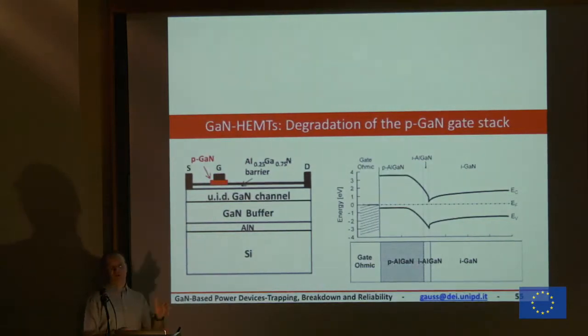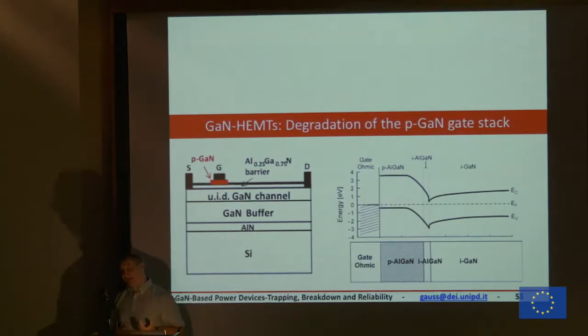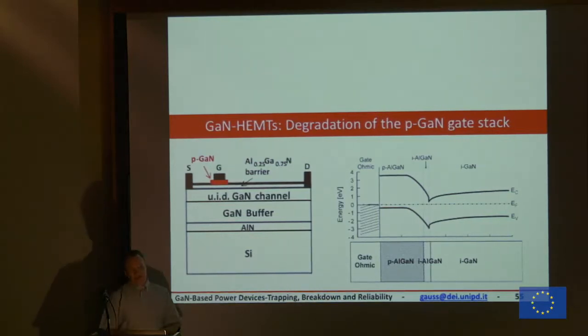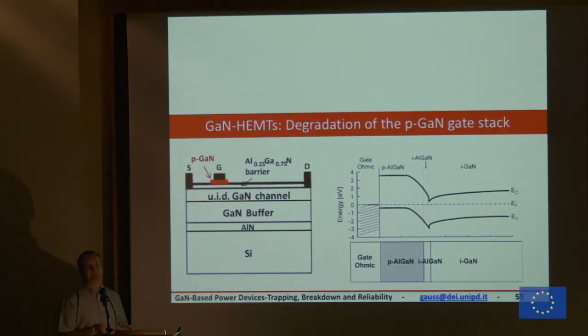So this was for what was observed in gallium nitride devices for RF condition, in the years 2008 to 2014, with a Schottky gate, suitable for RF application. Now let's go to what we are more interested in today, the device for power switching application. And yesterday you saw the presentation from Farid and Peter. They are speaking a lot about the P-gate. So let me show you a little bit about the P-GaN gate.